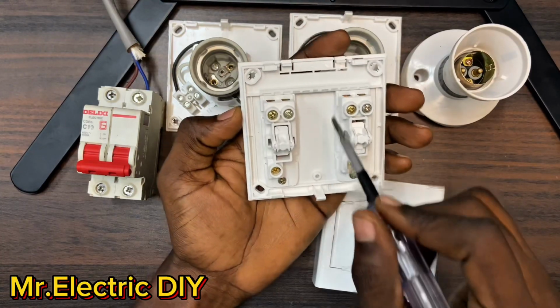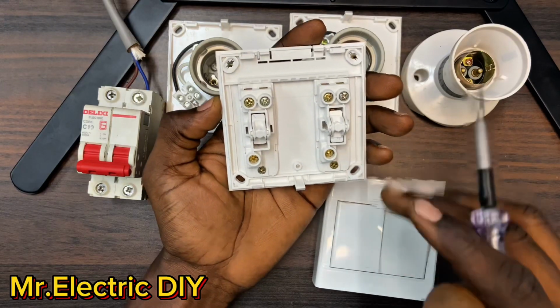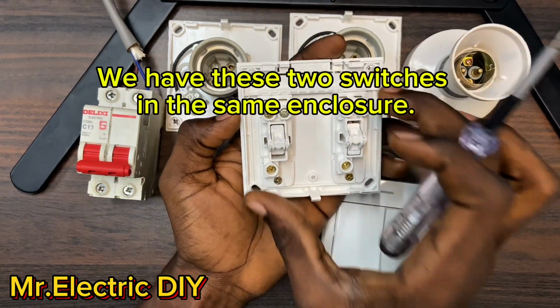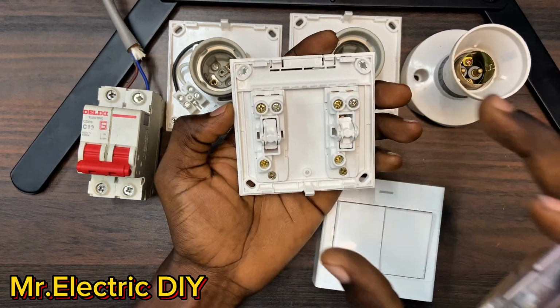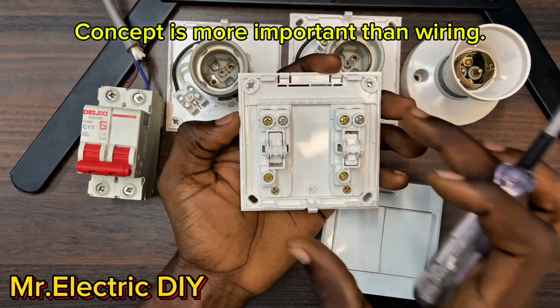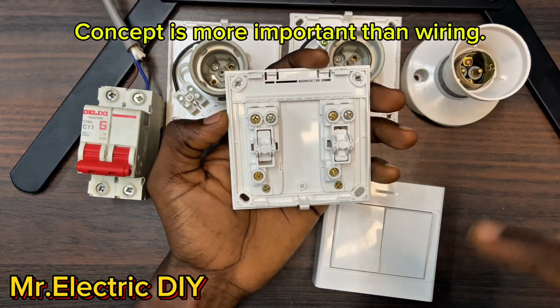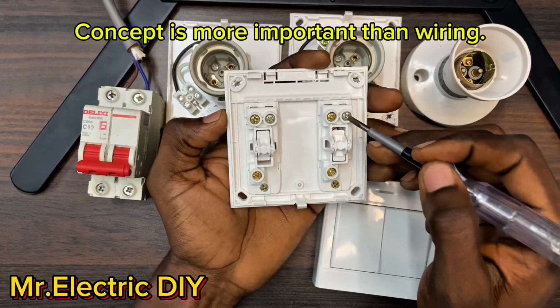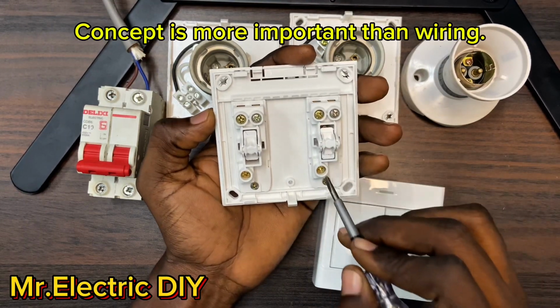This is actually a 1-gang 2-way switch, and this is also a 1-gang 2-way switch, but we have these 2 switches in the same enclosure, so we could call it a 2-gang 2-way switch. Others might also call it a 2-gang 4-way switch. It is the same thing because we have one terminal as the common or the live, and the other 2 as L1. This is L1 and this is L2.